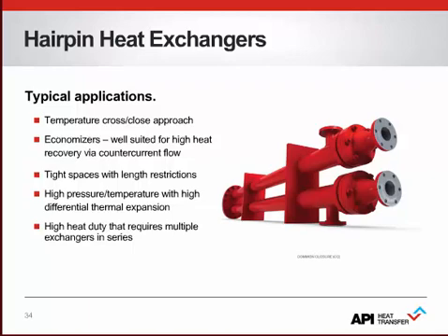Typically, an economizer is tasked with providing the most heat transfer possible for a given amount of surface area. For these high heat-duty applications, a hairpin is a great solution. A consequence of maximizing heat transfer between two fluids is that a tight temperature approach is created. A hairpin design provides a better solution than a very long TEMA type, or again, multiple TEMA types in series, by limiting the footprint required for tight installation spaces.